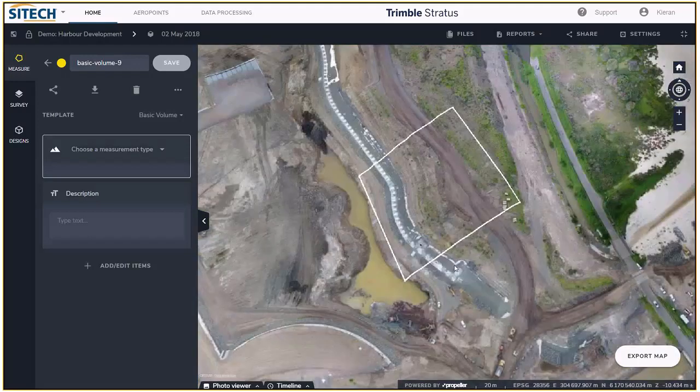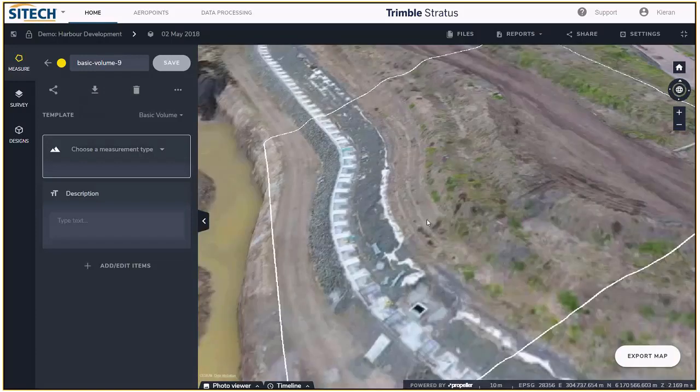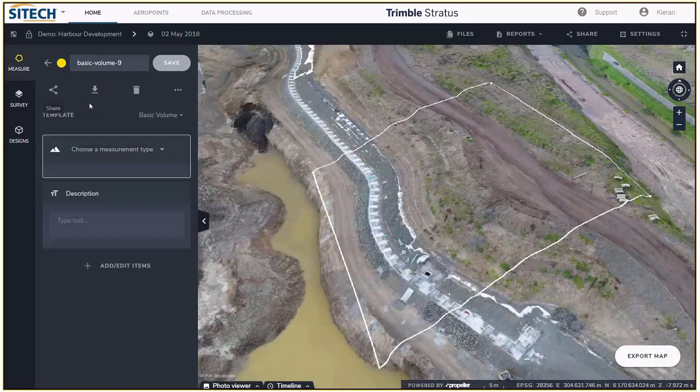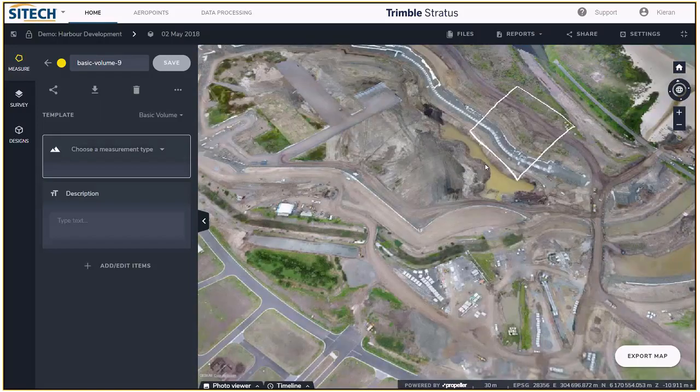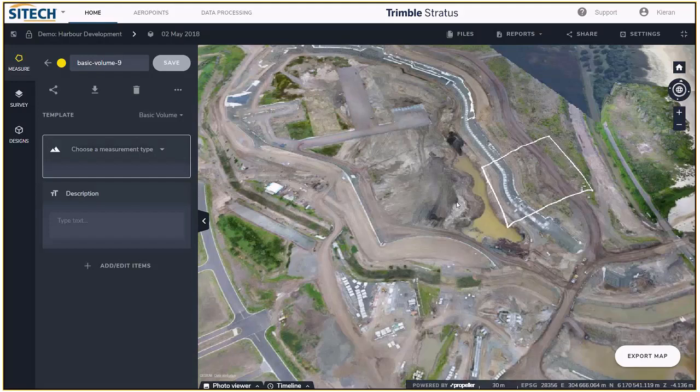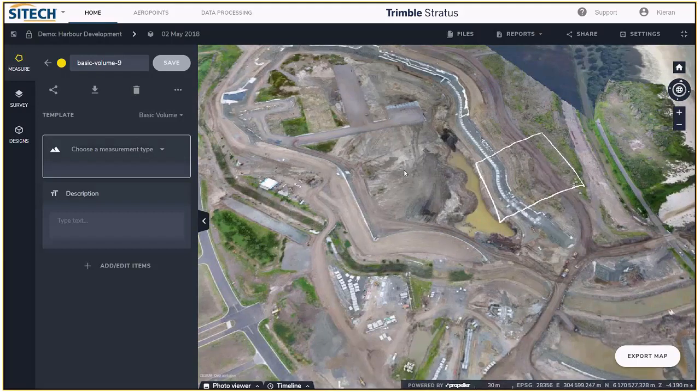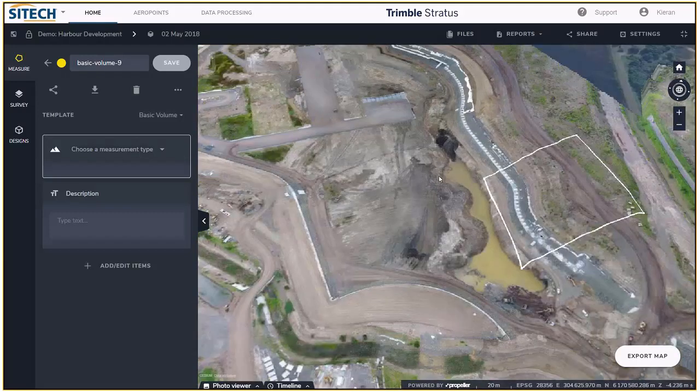So I could draw whichever number of areas I needed and export that and say, right, well, I know I can only really deal with 100 meg, so I'm going to sample that down to 25% and pull that point cloud out that way. In the Trimble workflow, certainly, one of the things that Stratus is not meant to do is create design files for us. Within our stable, that's still a TBC process. So we might use Stratus to intelligently take out the bits of data we want at a useful resolution, and then work that up into a surface and do our design there in TBC.